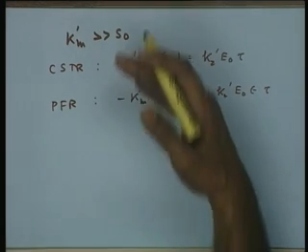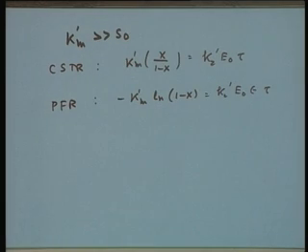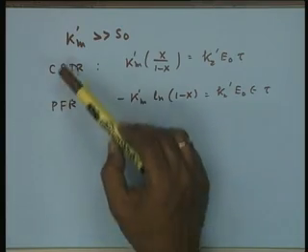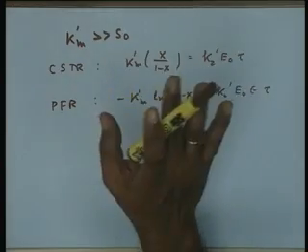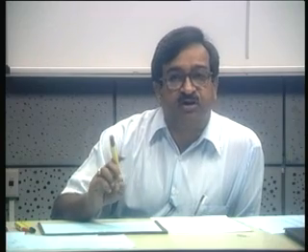Now, as I mentioned earlier, our interest will always be to have a high fractional conversion, that means most of the substrate which is being fed gets converted into product. If we want to compare the performance of both CSTR and PFR, in the case of zero order regime there is no change, the performance remains identical, that means the quantity of enzyme required will be identical in both cases for carrying out the same conversion and at the same enzyme loading.